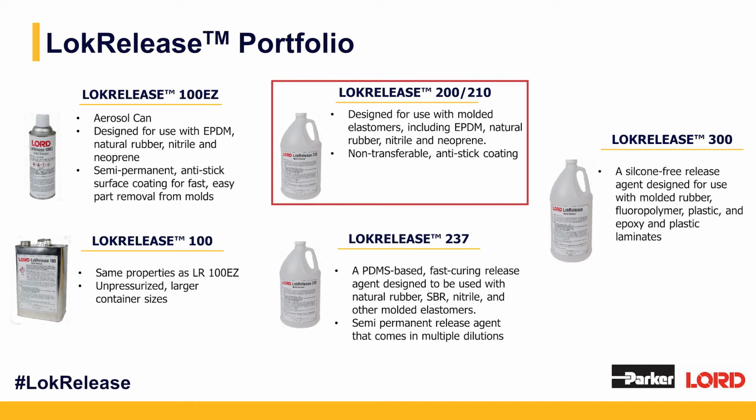Lock Release 200 and 210 provide a non-transferable anti-stick coating designed for EPDM, natural, nitrile, and neoprene rubbers. These water-based mold releases are designed for use in the manufacture of molded parts, as well as rubber bonding operations in injection, compression, and transfer molding.